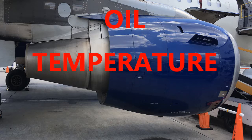Now the indication becomes amber, and remember with an amber light, you always have that pairing with the master caution light. The master caution light is going to come on when the temperature is higher than 311 degrees Fahrenheit. So we went from 284 degrees to 311 degrees Fahrenheit, where we have these markers of indication and warning colors. We have the flashing green at 284, and then it becomes amber at 311 degrees, when the master caution light will come on.